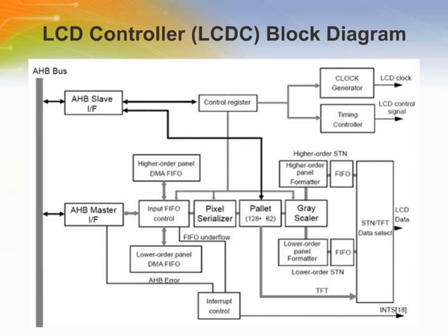This LSI incorporates a color-capable LCD controller, LCDC. It consists of a DMA, first in, first out, and related control logics, a pixel serializer, RAM palette, grayscaler, higher-lower order panel formatter, and panel clock generator.